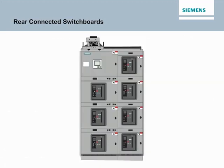Siemens rear-connected RCS switchboards feature individually mounted branch and feeder devices. Because of this method of mounting, access to outgoing cable terminations must be from the rear of the switchboard. Bus bar extensions from the feeder devices are run back to the rear of the unit for easy access. The front and rear of all sections align. Both indoor NEMA 1 or outdoor NEMA 3R construction is available.